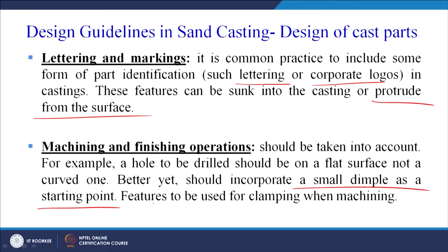That is a long story related to drilling, because the drilling chisel edge is not straight and there are chances of drill wavering when it touches the surface. So there can be a small starting point so that the chisel edge does not waver. We will discuss it in detail with the help of a diagram during our session on design for machining.